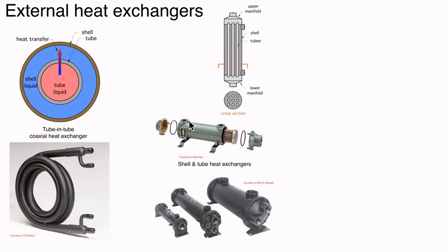Again, the two fluids for best performance would be going in opposite directions. Now, down at the bottom here, these heat exchangers are multiple pass tube and shell heat exchangers. So instead of having a manifold chamber on the opposite ends of the shell, both the inlet and the outlet for the tube bundle are on the same end of the shell. So essentially, the internal geometry sends flow down through the tubes on one side. Those tubes make a U-turn at the other end of the heat exchanger, and then the flow comes back and comes out the other end.